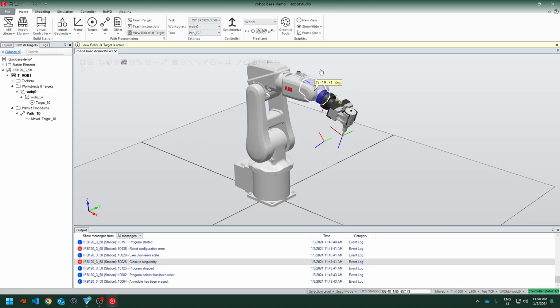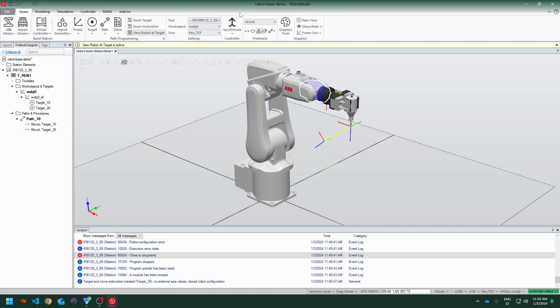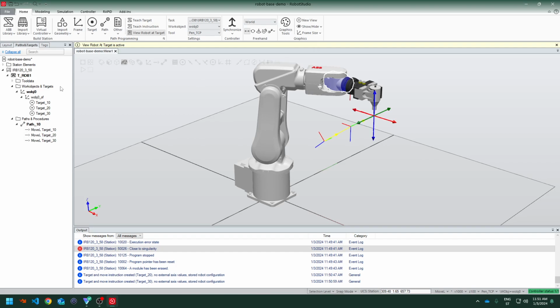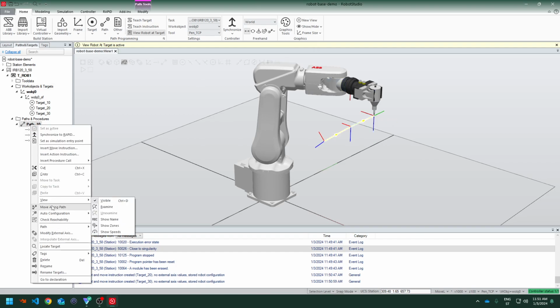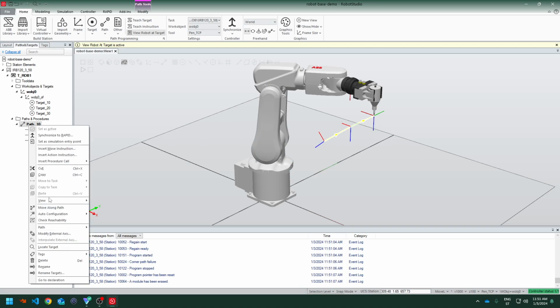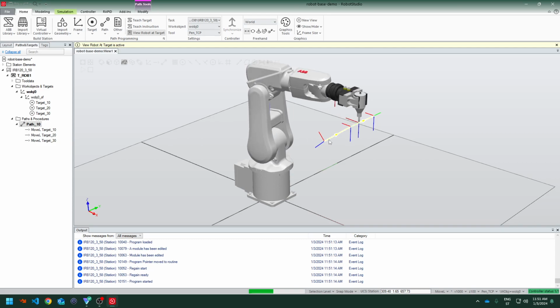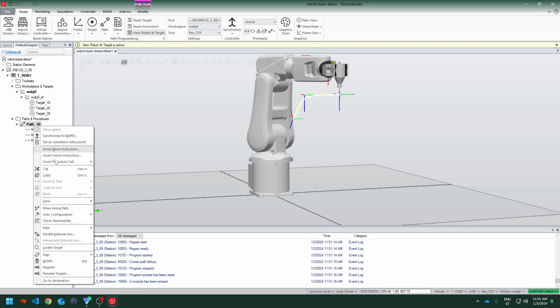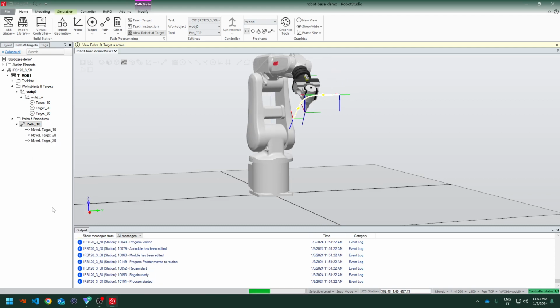For example, I'm going to go here instead. Teach instruction. And let's say move it here. And teach that instruction instead. Then move along the path, and now that the path is reachable, that I have corrected it, I can move it. It's going to go to the start immediately. This isn't the best way to see this, maybe like this, and it's going to go here.